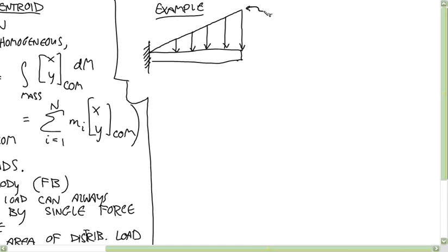And this point here has a value of 5,000 newtons per meter. Okay, so that's how distributed loads are always going to be reported. And that means that given the length of this, let's say this is 1 meter long, you can, at any location along the length, figure out at that point what's the magnitude of the distributed load, right?